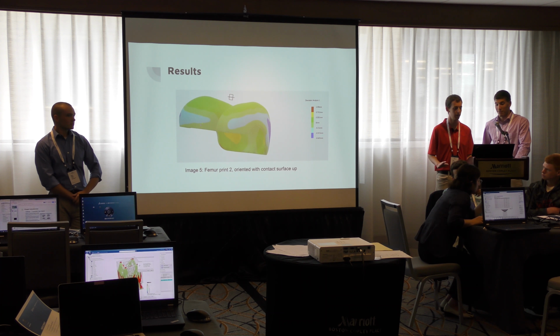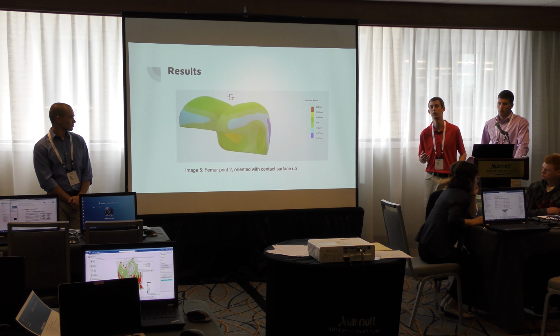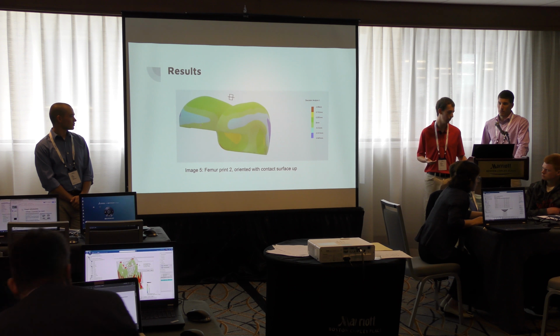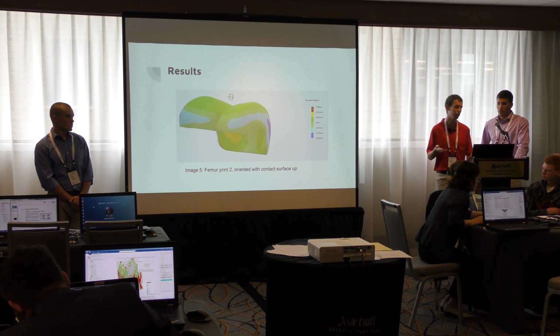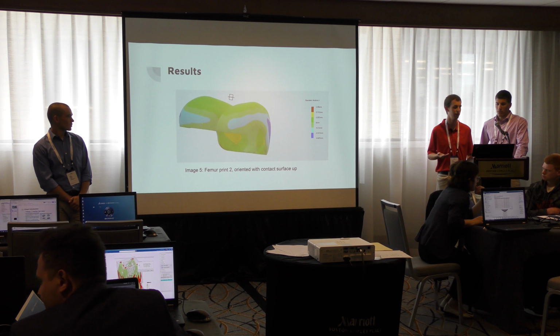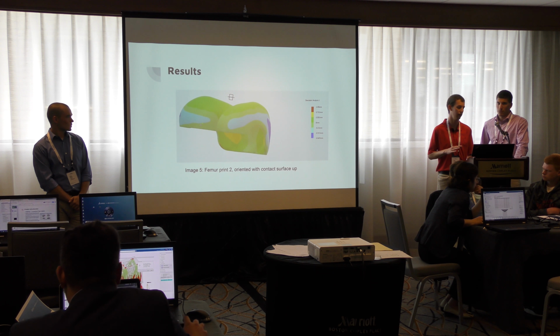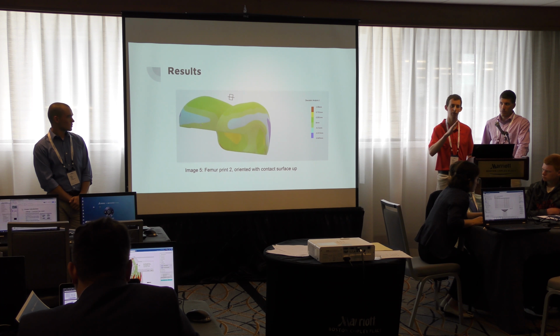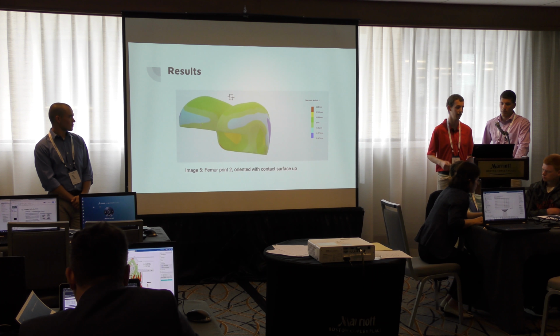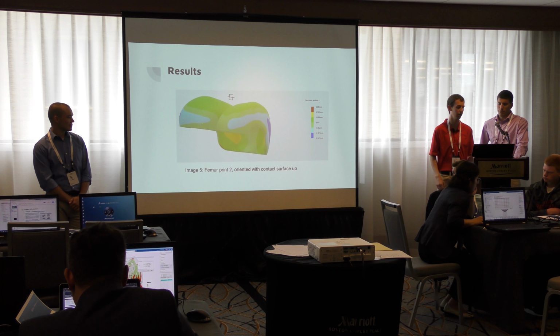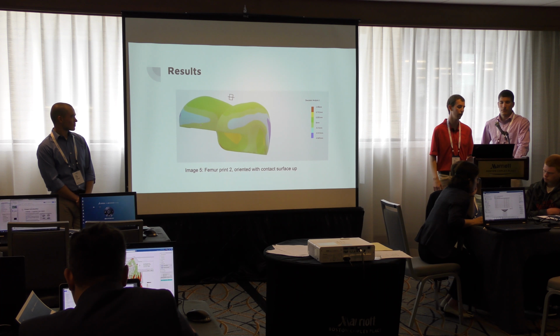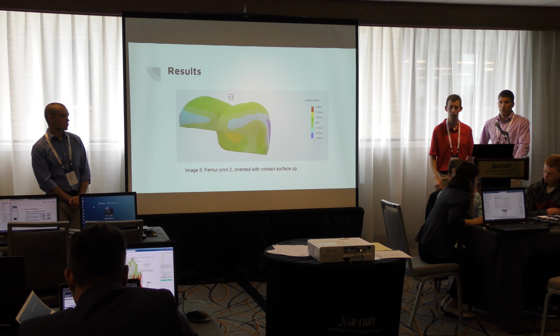Okay. So we also ran face down, so then the contact surface up. And so there would be one easier post-process for this particular orientation is that there wouldn't be any support structure on the inside surface, on this concave surface on the inside of the insert. So that would greatly improve post-processing and ease of manufacturing.